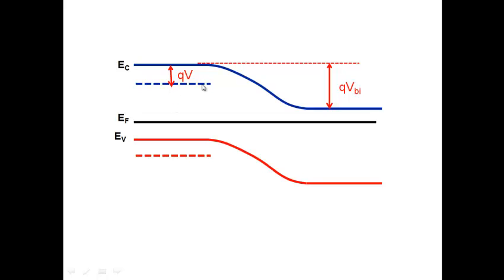Now I connect it by a smooth curve here. Far away, my N-type will remain N-type, nothing will happen here, so I can even draw a Fermi energy depending on the doping. This side remains the same, and I connect by a smooth curve.